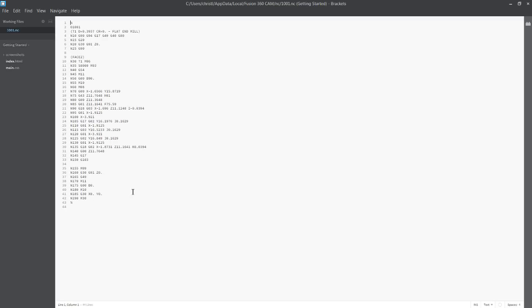Now this is a very short program because we don't have much in there. We have a facing operation. But what I want to highlight is, first of all, we're using G54. That was what we wanted in there. We are using B90 rotation. So it actually starts out calling out G54. It rotates 90 degrees. This is what I want you to keep an eye out for.